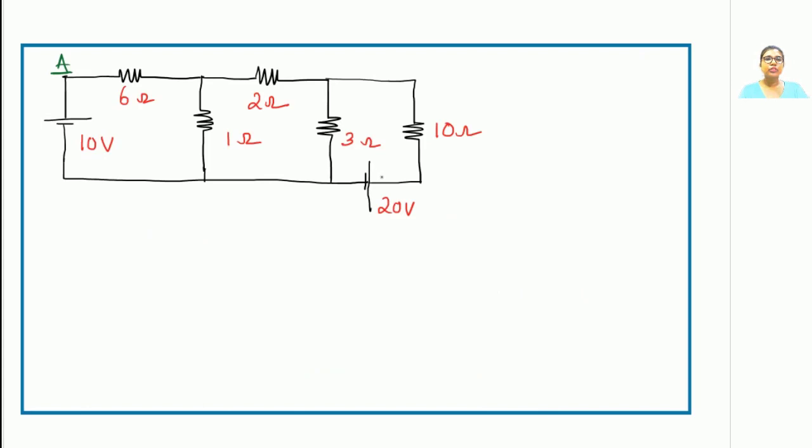Now let us move on to the question that was being asked in our first slide. You already know the basic idea of how to solve these equations using mesh analysis. First, you need to identify the meshes. If I ask you how many loops there are, then naturally there are more than 3. It's a task for you to find out how many loops are present in the given circuit. But if you talk of meshes, or the smallest loops, then certainly there are 3 meshes over here. So there will be 3 mesh currents, 3 unknowns, so 3 simultaneous equations.